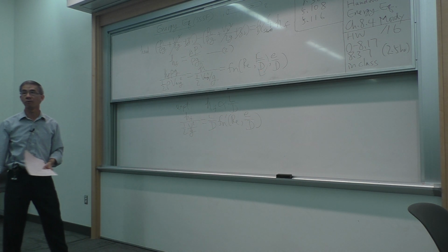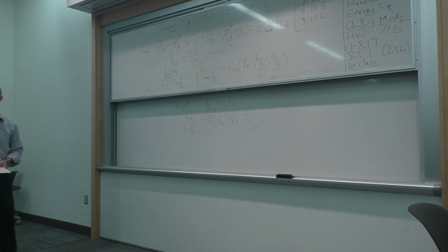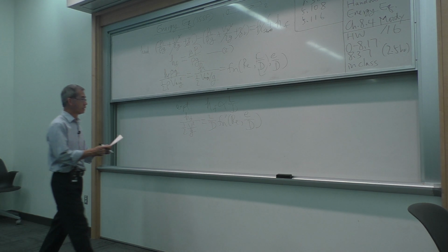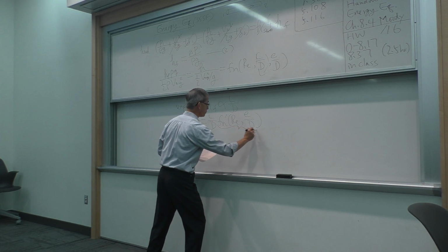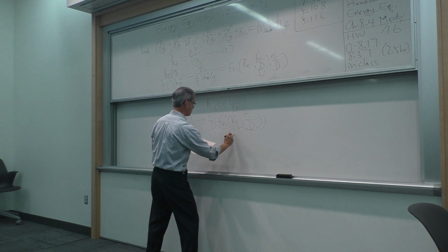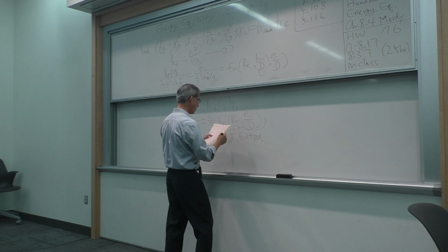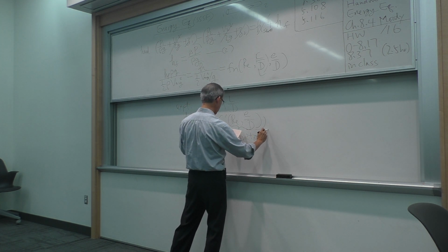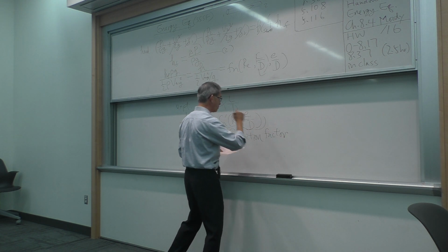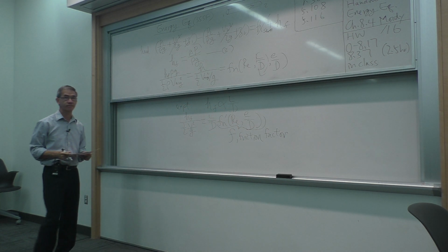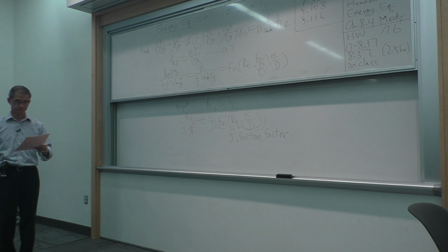Just take it out, because I know by experiment, again, not by dimensional analysis. This is after I've done a lot of testing in my laboratory, and it's kind of what you do in the homework. I've observed this is now my final form of the relationship, and this function of Reynolds number and roughness factor is what I will plot in this famous Moody diagram.